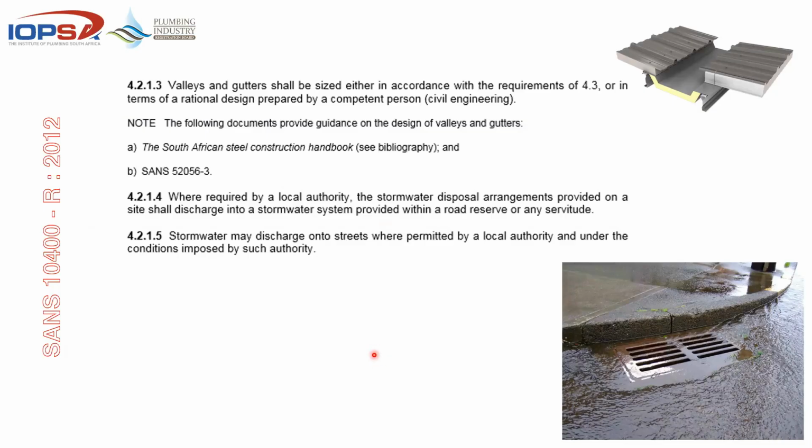You'll see a lot of building plans and a lot of correspondence from council refer to overland flow. Most of us are familiar with the fact that you cannot block overland flow. So if you're living on a sloped site, you can't have a wall at the back of your property preventing the overland flow from the neighbor behind you, which would build up against that wall and then collapse the wall or cause flooding. We need to provide for overland flow under general conditions for the water disposal.